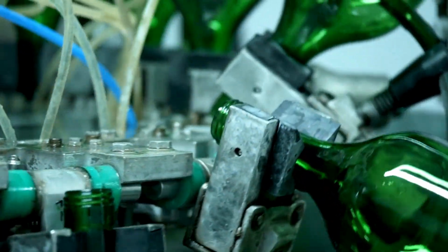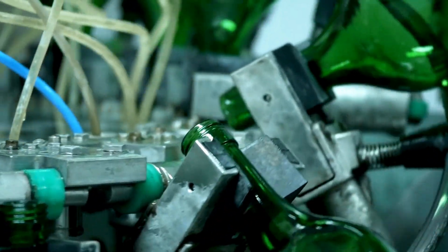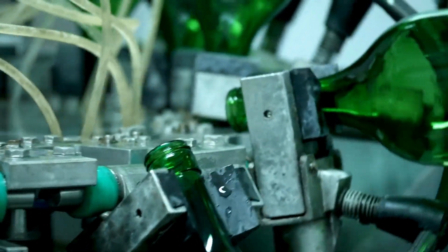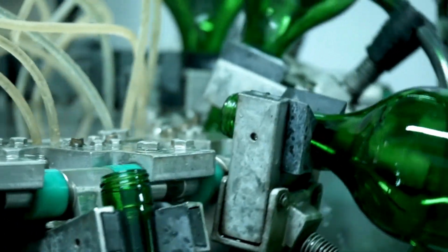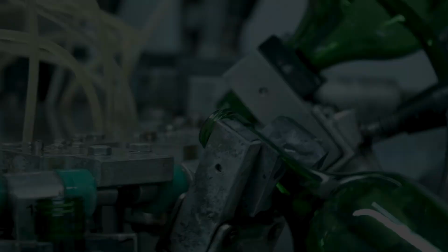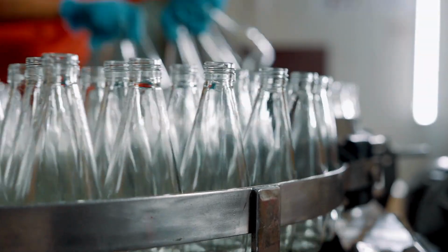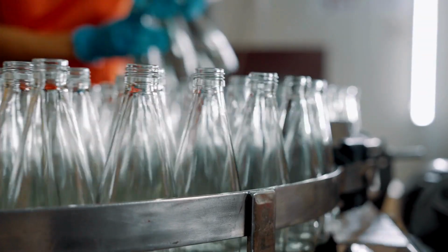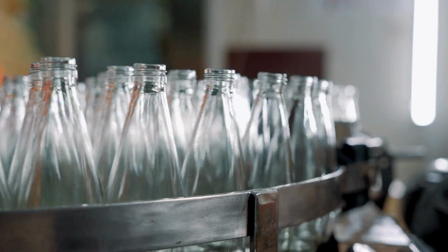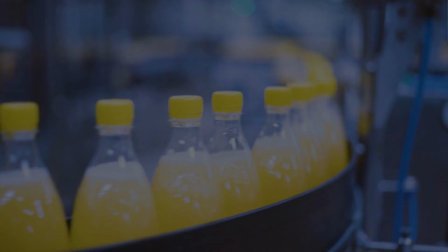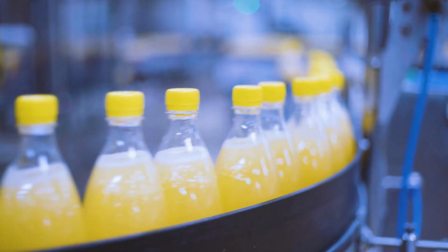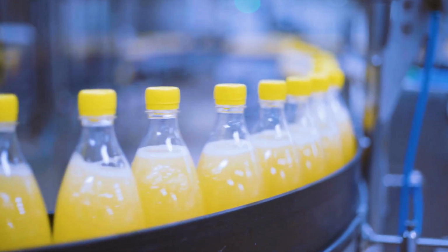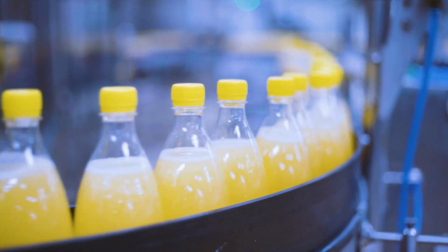In our OEE sheet itself, we have a list of every single fault, every single failure, and every single reset and how long each of those took. We took all of that information and correlated it into the model. So as the model is running, we can easily grab reports like, what was that failure and why did it take so long? Or what was the failure that occurred most often? And compare that to the analysis that we got from our line audit.